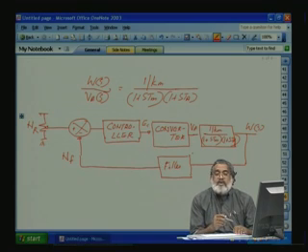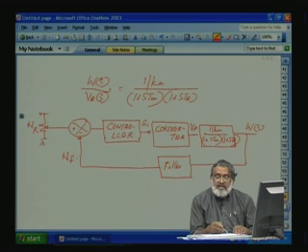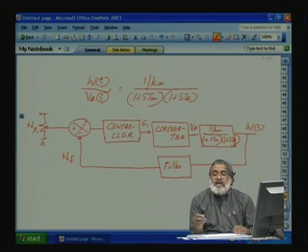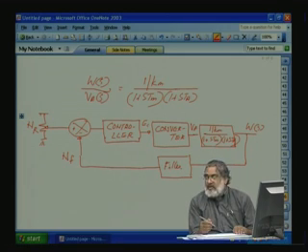Same like our phase control converter, outer voltage loop and inner current loop. So there is an inner, fast acting current loop, because that has to be very fast. Any change in the omega s depends on the mechanical time constant. So VA has to be controlled depending on the current requirement of the machine. So we have to modify this block diagram and introduce the inner current control loop, and then find out the controller.